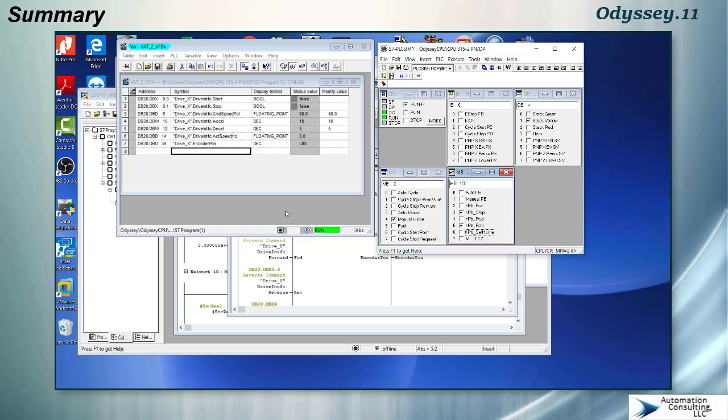Of course, a servo, I could simply tell it that I want it to go to a position of, I don't know, 3 meters or something like that on an actuator, and the encoder count would be scaled, and it would stop probably within a couple of millimeters or even micrometers of the correct position. But you can't do that with a VFD, which is why I was asked this question in our little Facebook automation group, which is what inspired this series.